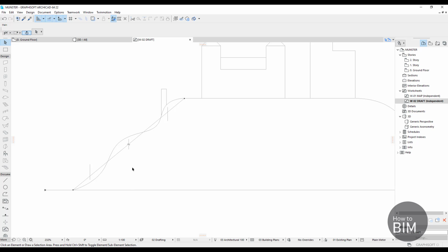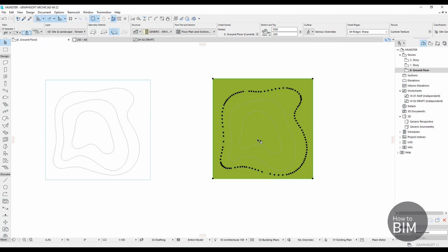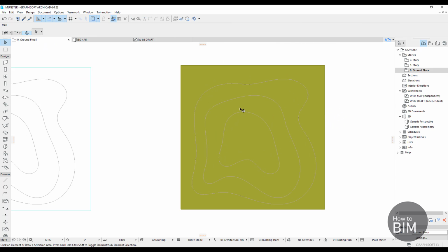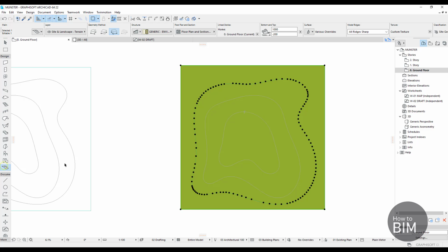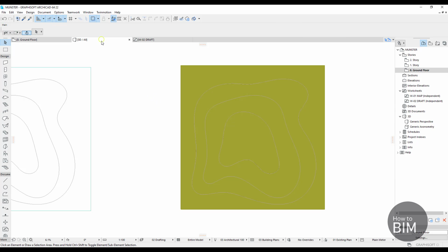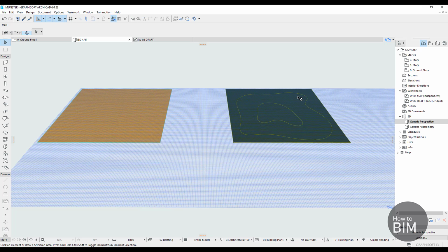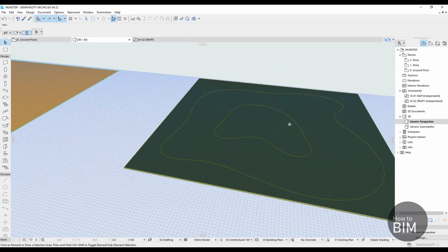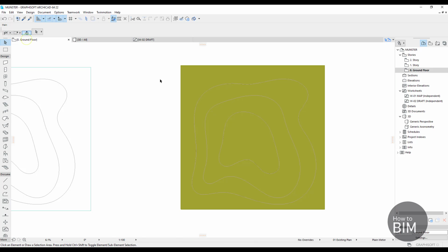So if you choose the option Fit to User Ridges, that means that it will just create the spline as a projection. Okay, I will show you, maybe it will be easier to understand here. So I will click on the mesh, select the mesh tool, and hold spacebar, left click, Fit to User Ridges. Okay, I go to 3D, and as you can see, now our mesh has these points. They're in our mesh.